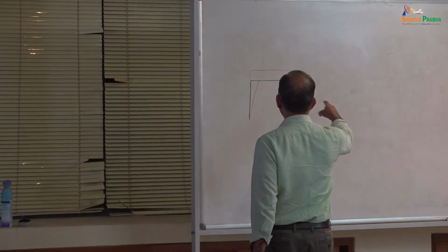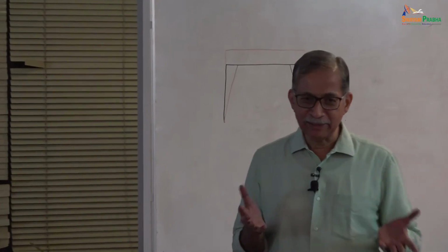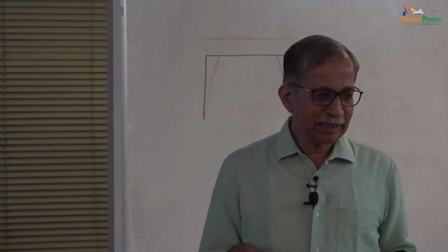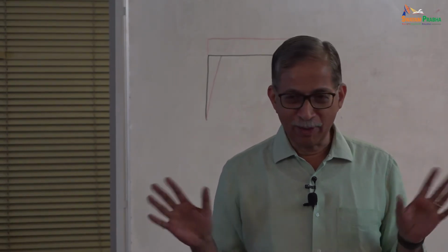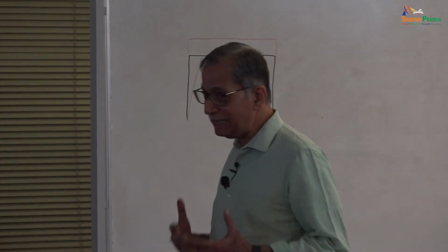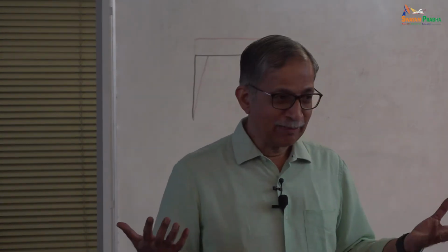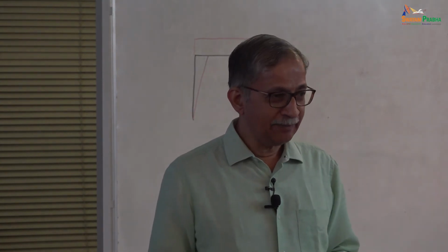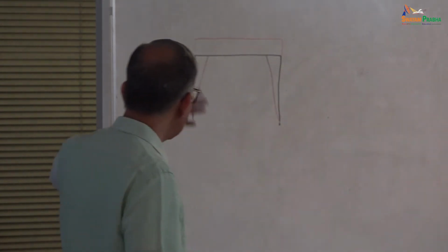The rule is we draw the bending moment diagram on the tension side, right? Well, you can draw on the compression side, but whatever you do, you must do consistently for both beam and column, for all elements, right? This picture is wrong. Why? The reason why in India we suggest you draw on the tension side is, if it's a reinforced concrete building, you know on which side, top or bottom, to put your main steel. This is hogging, so you need steel on top. That's why you draw the bending moment diagram on top.